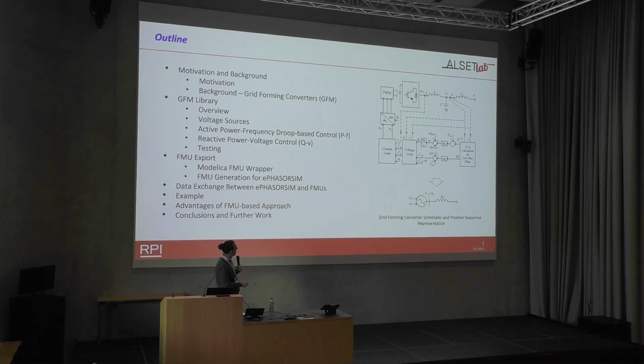What you will see inside of these things is that you have to take some measurements, and then you have different cascading control loops until you arrive at the PWM. Now, simulating this for large system simulations is quite a challenge for domain-specific tools that have been built to do that. Modelica tools would do okay anyway, but when you're talking about having many of these models, it becomes very hard.